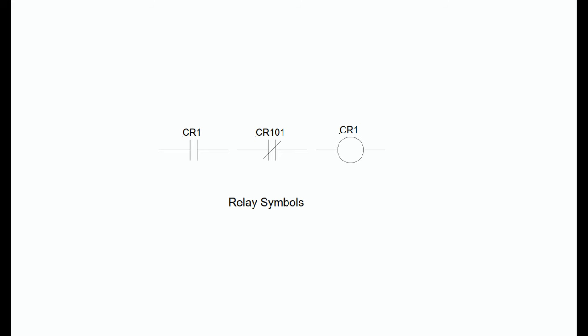Notice that the normally closed and normally open contacts of the figure each have lines extending from both sides of the symbol. These are the connection lines which, on a real relay, would be the connection points for wires. The reader is invited to refer back to the figure and identify the relationship between the normally open and normally closed contacts on the physical relay and their corresponding symbols in the figure.